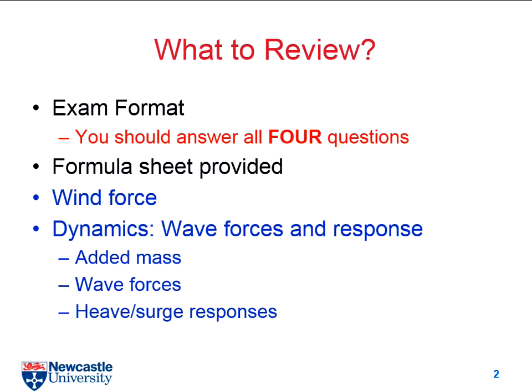Well, about the velocity, of course, it's the average speed of the wind, and about the density, of course, it's wind, and we use the density of air. You can use the value 1.225 or 1.23. That's fine. It's kg per cubic meter. And I think in your exam papers, if you need this density, I will not give you the values because it's a very basic value. So you can use a value like this. It's fine. And when you use the density of water, you can use 1,000 kg per cubic meter or 1,025. That's fine. Both of them will be okay.